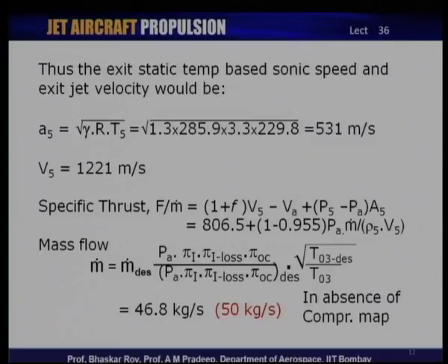discussion. If we look at the mass flow that needs to be calculated, again if we had the compressor map, or the turbine map, or the maps of intake, compressor, turbine, nozzle, all of them available with us, we can have a coordinated configuration of the engine from which we can get this off design mass flow.